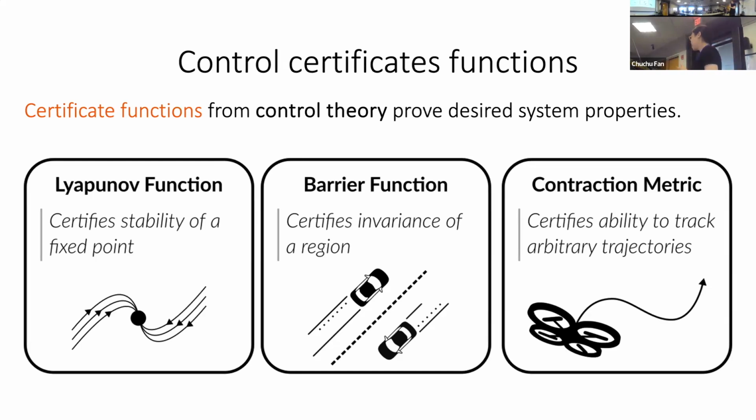And if you work on safety problems, you probably have worked on barrier functions. It is similar to the Lyapunov function, but it creates a barrier to tell you which is safe, which is unsafe, what's the barrier between them, and how to make sure you always stay within the barrier. A lot of people call this barrier an invariant set or forward invariant set. All these concepts in control relate to the same thing. And if we manage to find a barrier function, we can show the system stays within a safety set and prove safety.